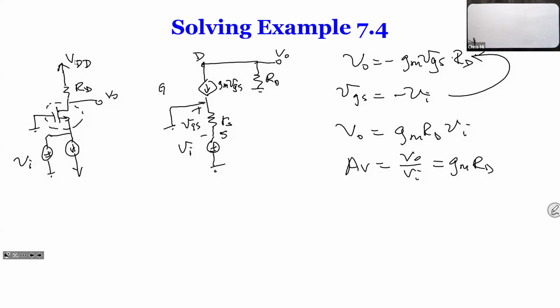Yes? The current source is the DC current source. A DC current source is an open circuit for small signal. We always treat this as doing superposition. The small signal is a circuit with the small signal superposed on the DC signal. So DC is open circuit for current, and voltage is short circuit, like VDD becoming a ground. The current source becomes open. In small signal, the DC current source is an open circuit, and a DC voltage is a short circuit. It's like you're taking superposition, right?